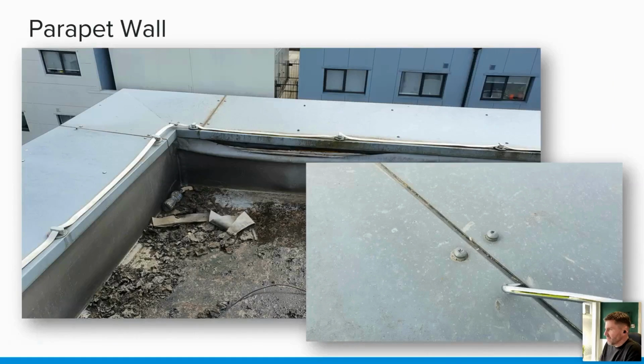Like I said, an example of a metal cap in there that you might see on a roof. Single ply here, the single plies come away from the upstand here, and when it comes to metal cappings, it's important to look at the joints and the fixings and make sure that all of that is not contributing to any kind of water ingress as well.